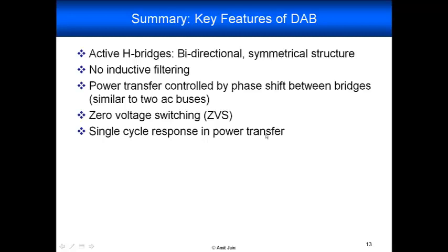We have lagging current in the bridges, and therefore we are able to get zero voltage switching. Because we don't have an inductive filter, we are able to get a single cycle response in the power transfer.